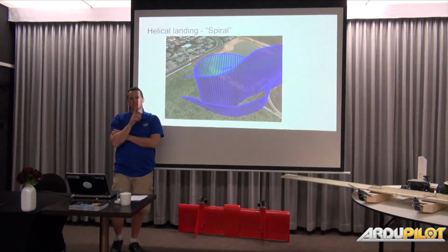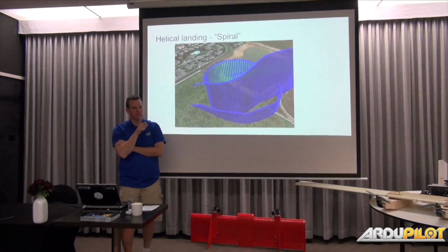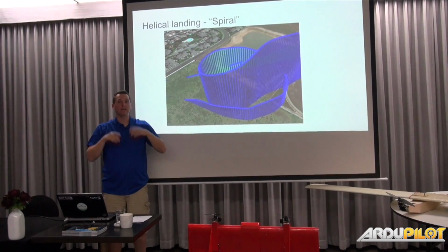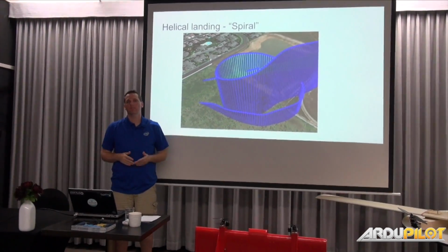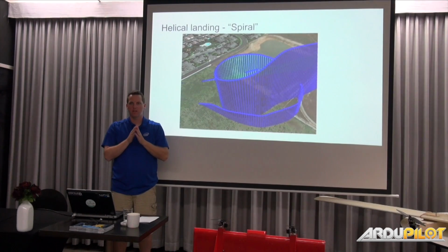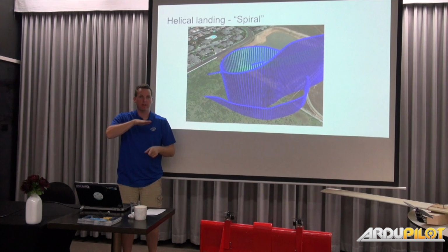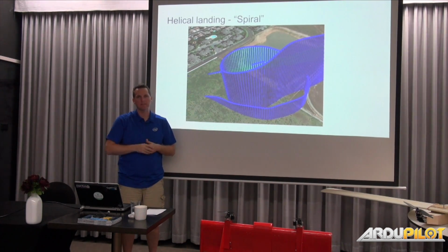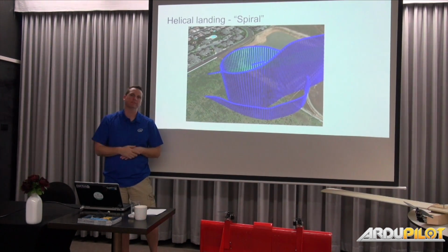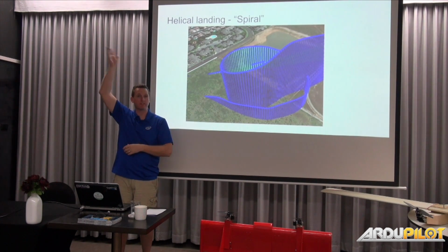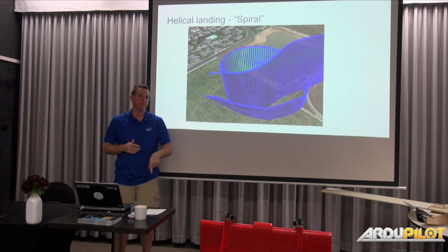Yeah. So deep stall. One thing about deep stall is that once you trigger the deep stall, you've done your wind estimate beforehand, and you're just gliding into that point. Some things we want to expand a bit is to be a bit more of a fly-by-wire-ish mode. So when you do that, you can actually still navigate and try to hit a spot more precisely, all the way down. You kind of just fly around. So it's sort of like a deep stall flight mode of sorts. So you can deep stall from 100 meters up and just get right there, and it'll happen right at that spot.